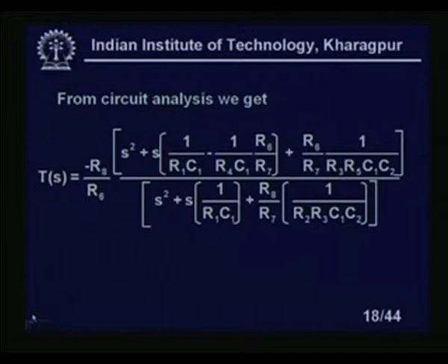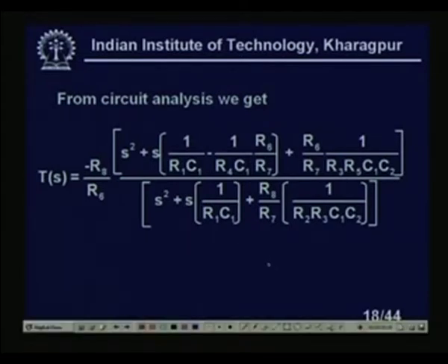Now, you see here, so for K we are using R8 and for omega z, R3. Let us look at, you see that K to R8 is changing. Okay, I am getting the proper value of R8 by tuning to the proper value of capital K. This is because K is equal to R8 by R6, is it not? So, I am tuning R8 to get the proper value of K, but you look at that R8 is also present in the expressions of omega p. So, omega p will change, right, it does not matter, let it change. Okay. I will bring it back to its desired value by using some other elements.